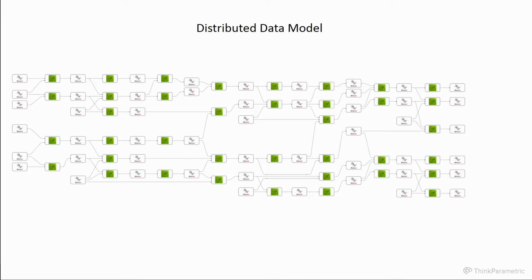As I will show later, it typically takes a few modeling steps to get to a specific representation of an object. By separating these steps out into individual models, anyone, at any time, can have access to each step of the generation process for each type of object in the model. Each task requires specific inputs to be able to generate the output. These inputs can now be mixed and matched from a myriad of models that all contain coordinated information. Using this principle, you can easily scale up your project, with the only limitation being disk space.